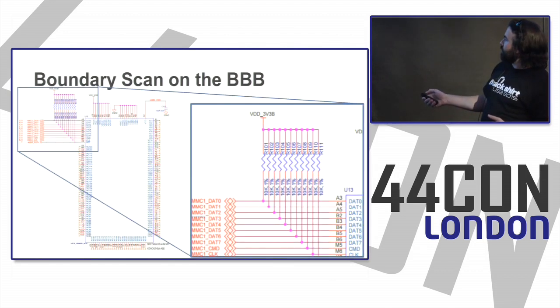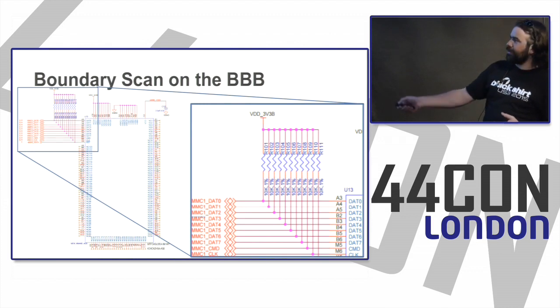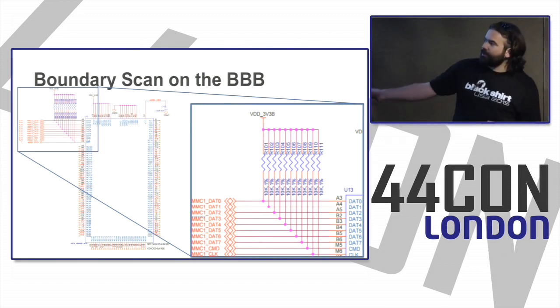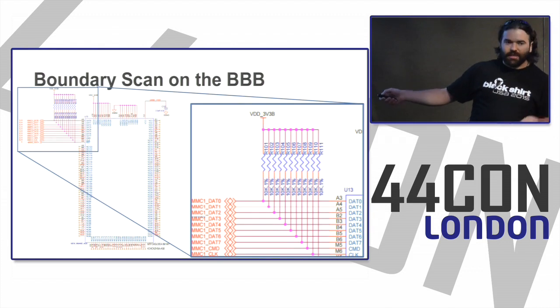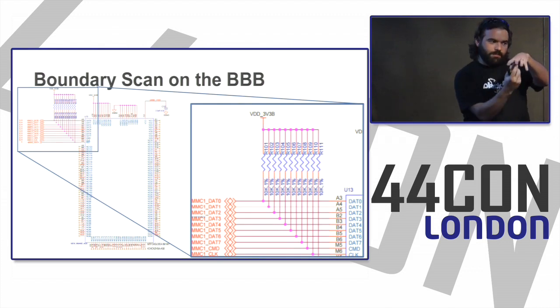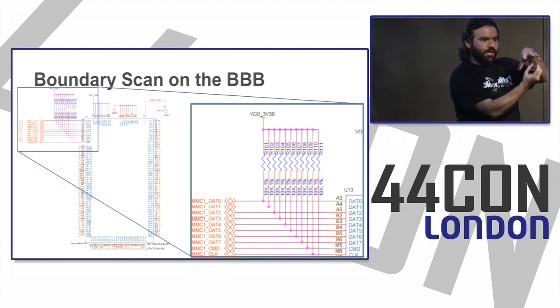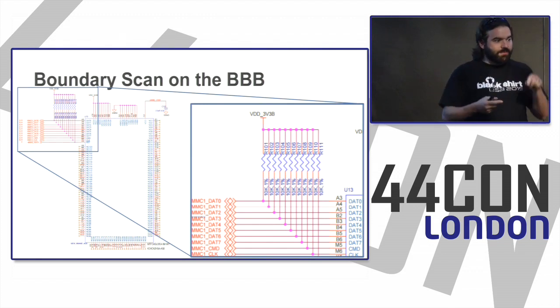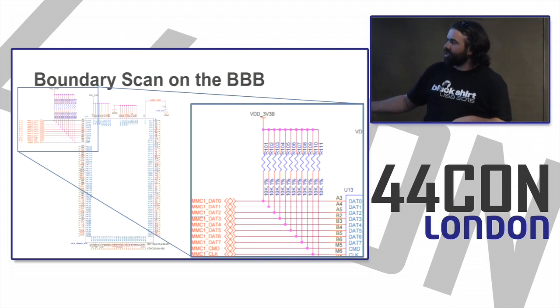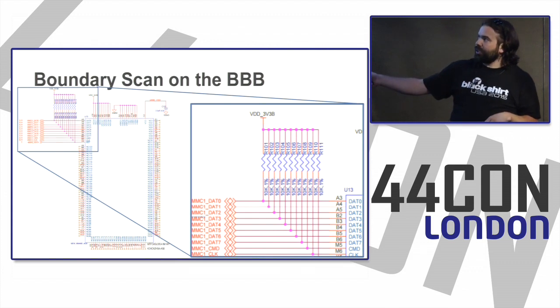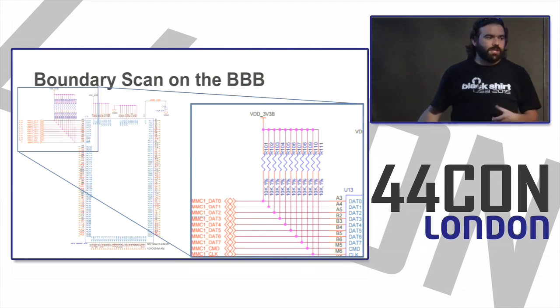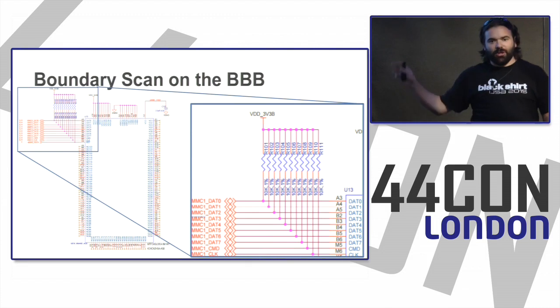Yeah, so what am I showing here? MMC pins. Oh, this is the bottom of the MMC chip itself. It's a BGA chip, meaning all the pins are little balls of solder on the bottom, so you can't actually access them from the board itself. You can also see there's a ton of pins, but we're only using about 10 of them, which is really nice about eMMC, because you don't have to worry about all those other pins.